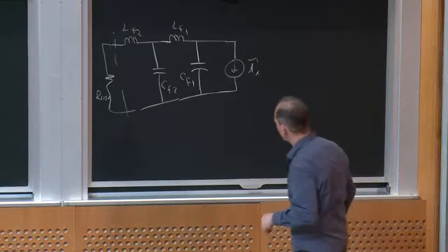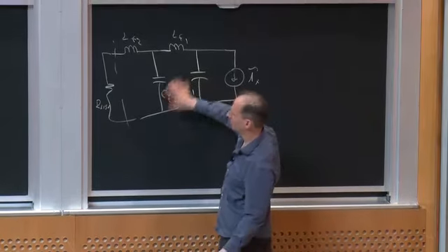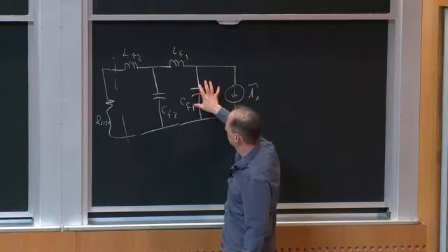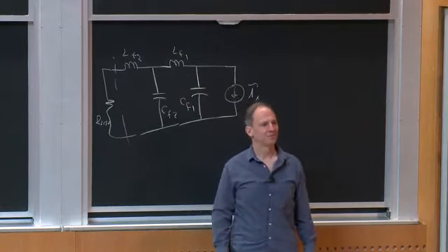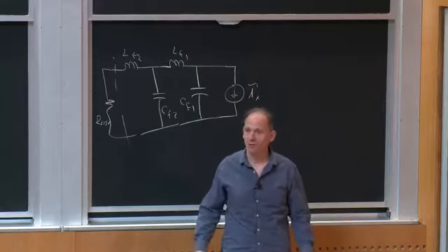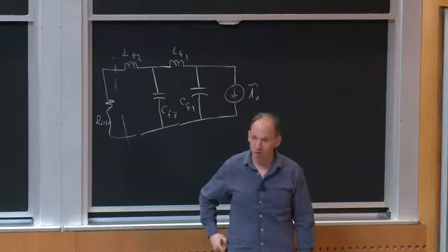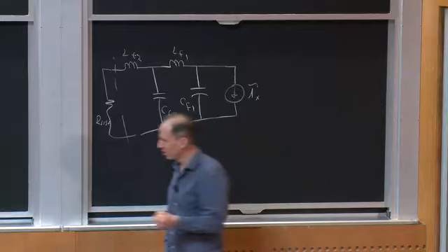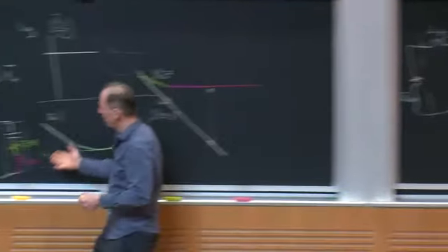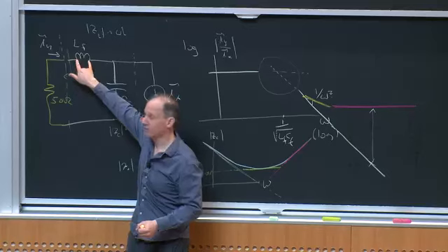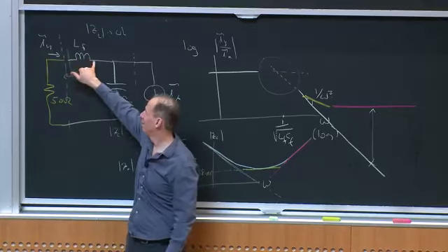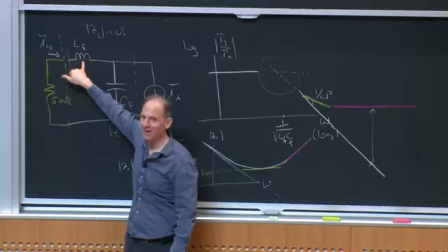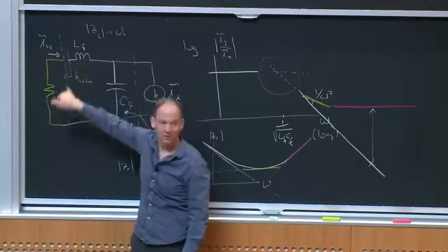So think about this. This filter in its cutoff regime, putting aside these parasitics I was talking about, could give you 80 dB per decade, right? You can get really lots of attenuation. And that's good because you need a lot of attenuation. But what's the downside? Well, one thing is the component parasitics themselves. And I focused on the capacitor. The inductors do have a parasitic parallel capacitance. You also have to worry about that one, okay?